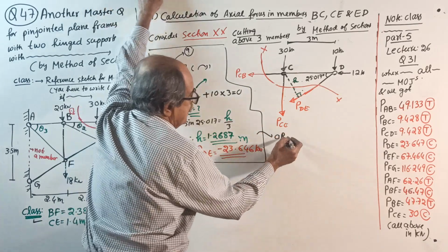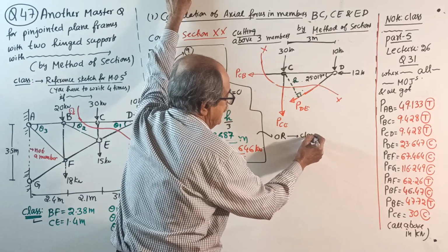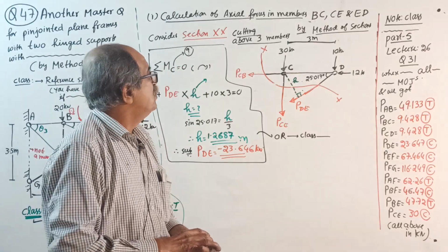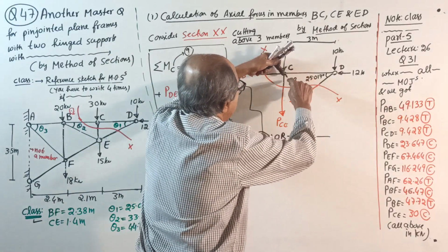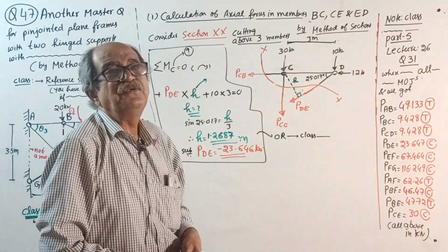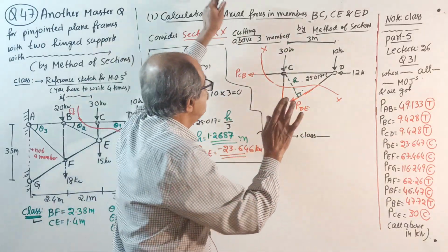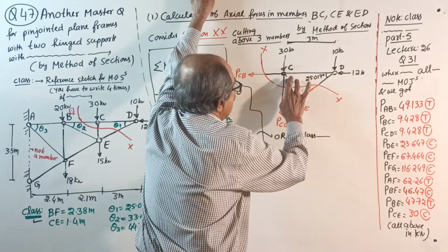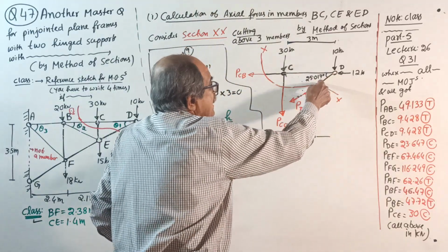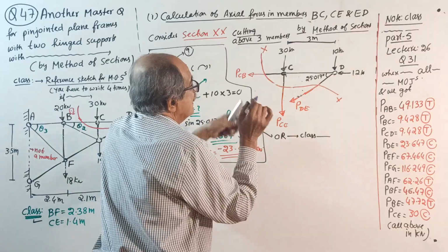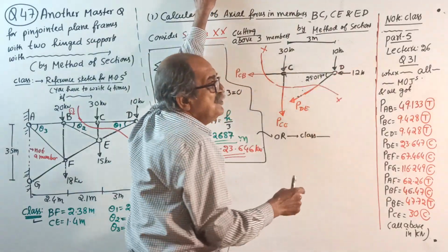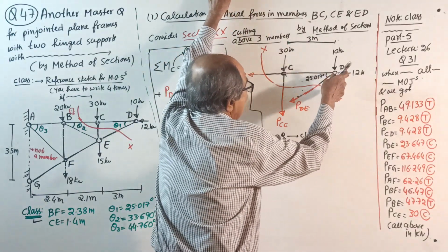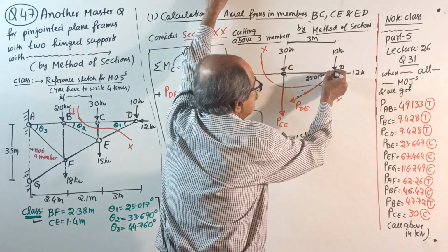Something I'm explaining now. There are so many people who get confusion. These perpendiculars are okay. In case you are getting confusion, what to do is, do not draw the perpendicular. Leave it, nothing required. For this inclined force moment you want, take green color. See the point through which it passes, any one point. It passes through D. Go to D and resolve this force into components.